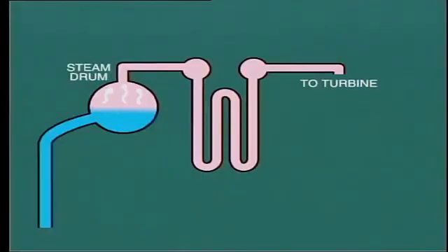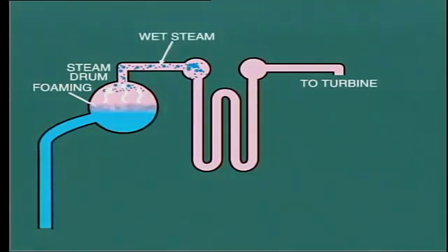The addition of trisodium or disodium phosphate to the boiler water does have some negative aspects. For one, it adds yet further solids to the water. In addition to this, it will affect the pH value of the water, and this may aggravate corrosion. We'll discuss this later. Another problem associated with high solids content in boiler water is carryover. The effect of the dissolved and suspended solids is to increase foaming on the surface of the water in the drum. This in turn leads to carryover of water with the steam.